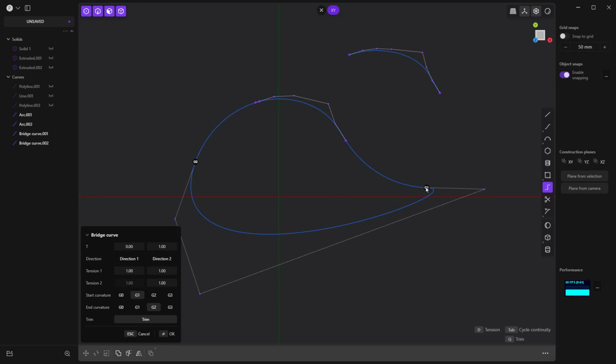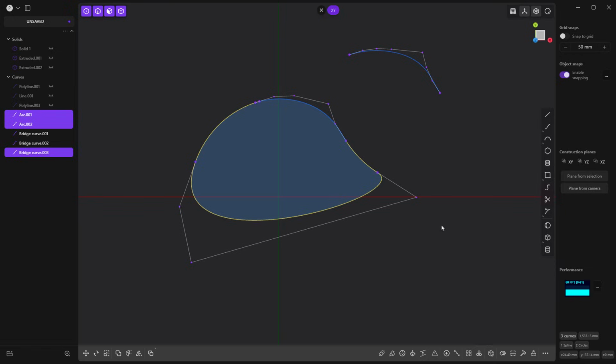because it allows you to determine where on those curves you can actually decide to place it. So for example, let's say on maybe this left side, I wanted it to be about halfway through. So I could go to about 0.5, but the bridge vertex is going to require us to go to the end of the original curve.